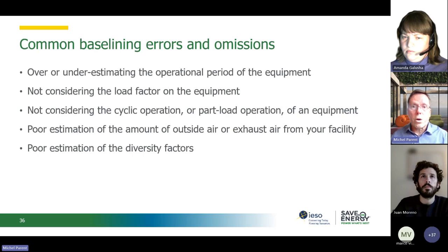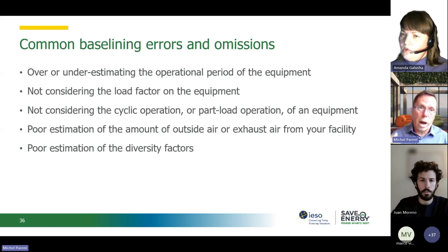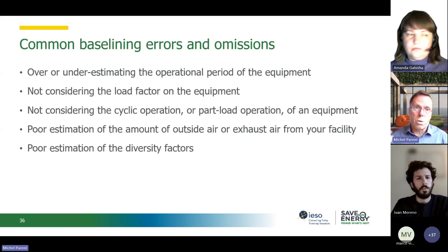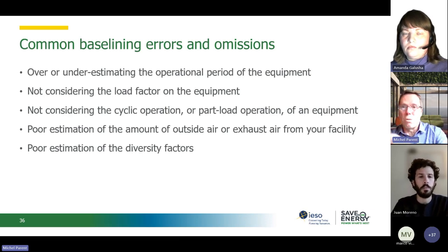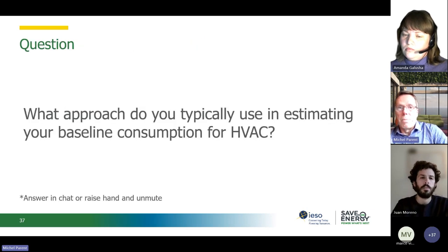Not having a proper load factor or equivalent full load hours can result in a really poor estimate of your energy use, because you're overestimating. Usually it's overestimating the number of operating hours. And if you're looking at demand, like I said, it's the diversity factor to say how much of that demand is on my peak. That's where you'll make the biggest possible error.